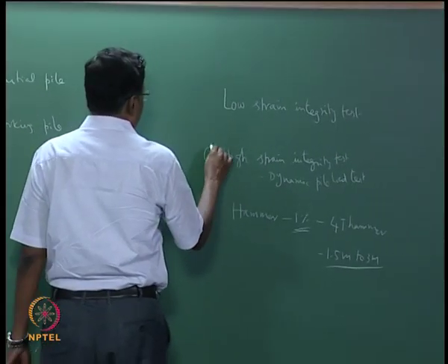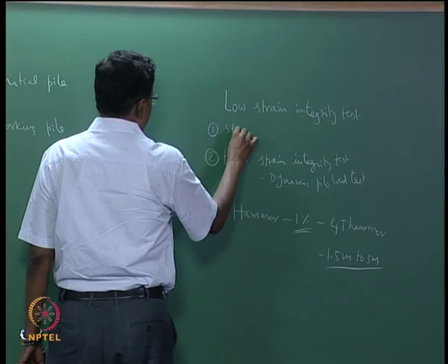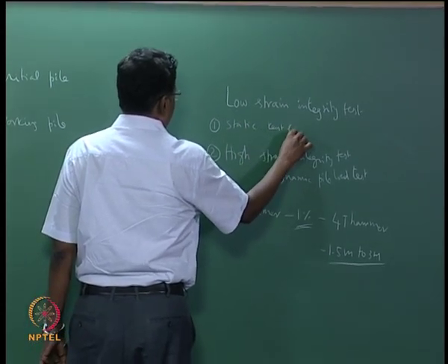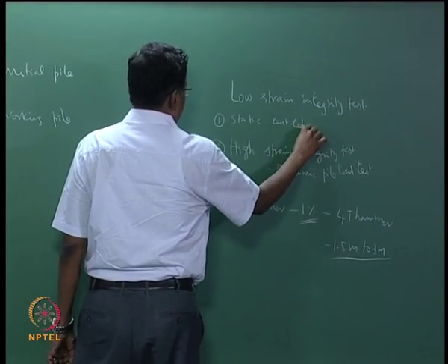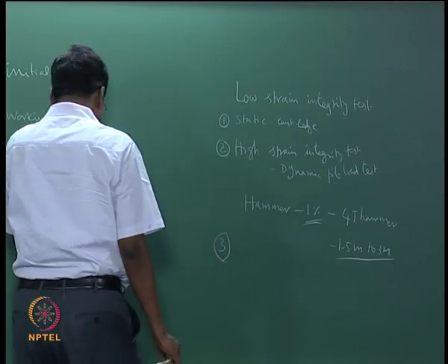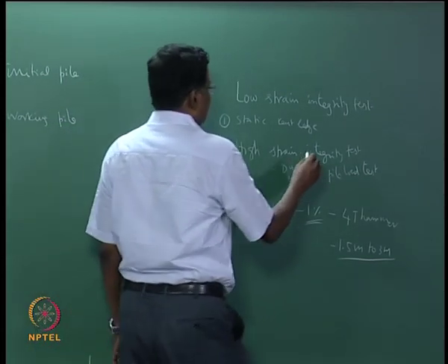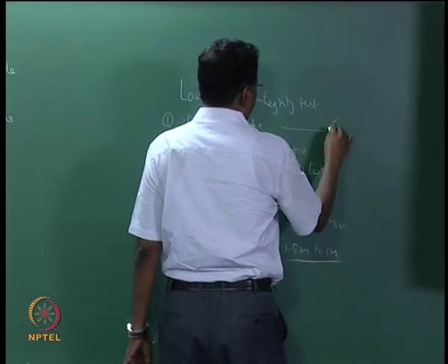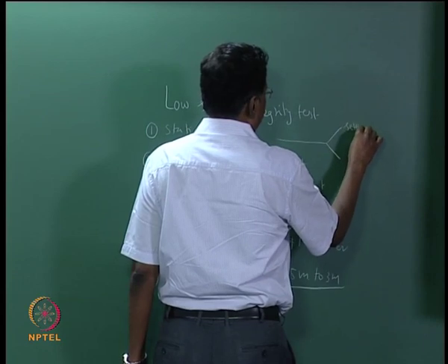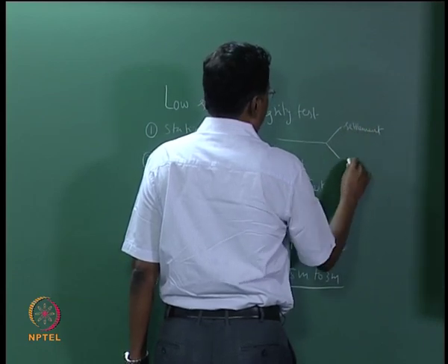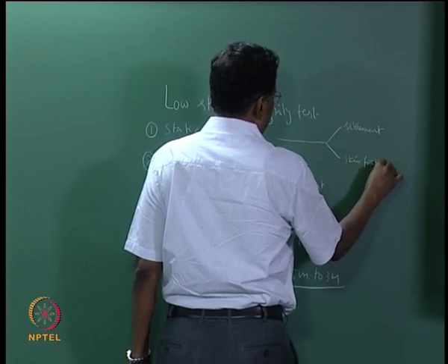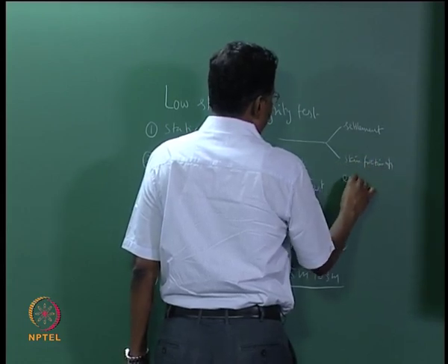So this is the static pile load test. The first one is static. Then in the static test also we have two types. One type is to measure only settlement, another type you will measure the skin friction and end bearing.